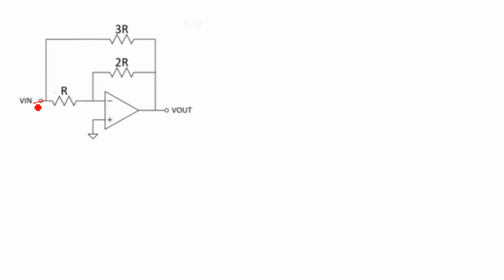So we need to find the input resistance across this terminal, hence we are connecting a voltage source Vin and grounding it. We also need to find the total current flowing through it, Iin. And obviously I'm just predicting, analyzing the circuit.